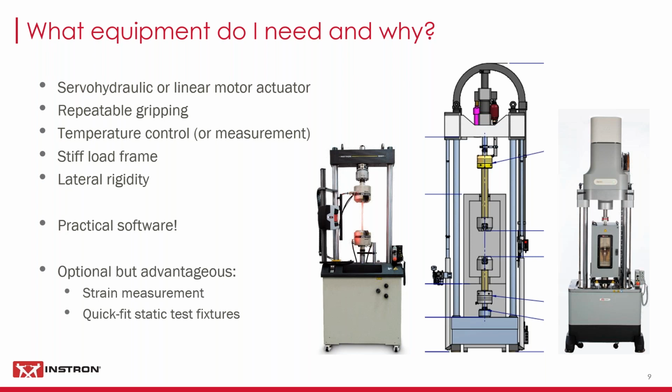A couple of comments at the end here. Optional things that you might want. They're not core to doing typical composites fatigue tests, but they can certainly expand your capacity, expand your capability nicely. One is strain measurement. That's in the sense of direct strain measurement on the specimen, whether that's with a video extensometer or a bonded strain gauge, or just a clip-on extensometer.